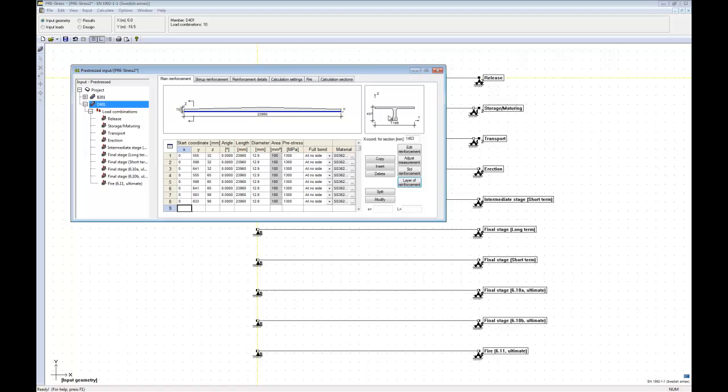So what we don't do with the T-beams here is that we don't calculate the shear force between the web and the flange up here. That might be something that the Eurocode says for specific for T-beams, but for these kind of elements we do not make the shear calculation up here in the cross section.